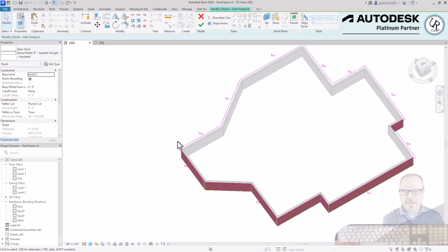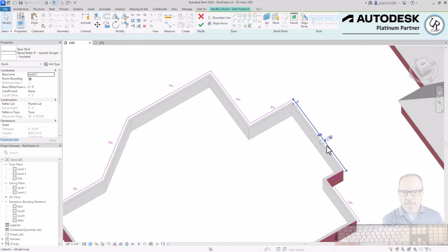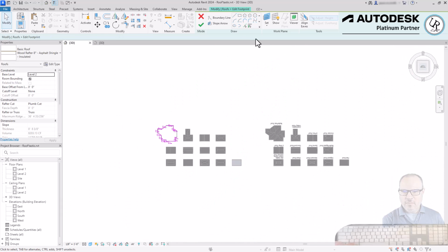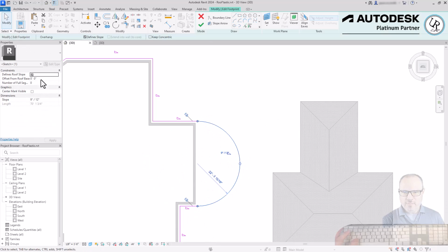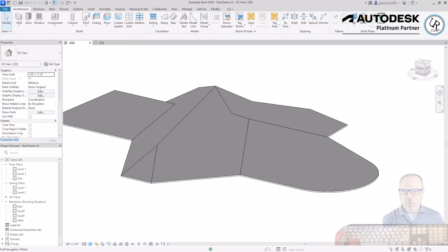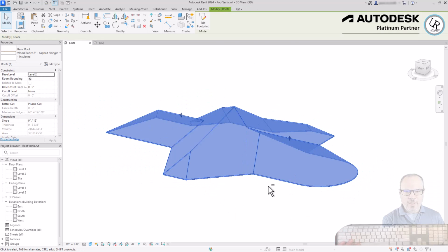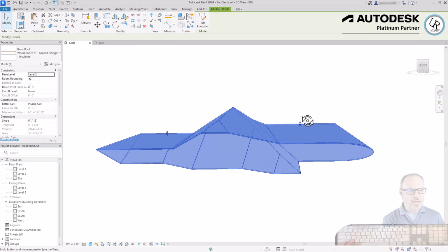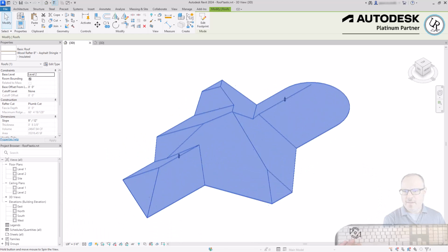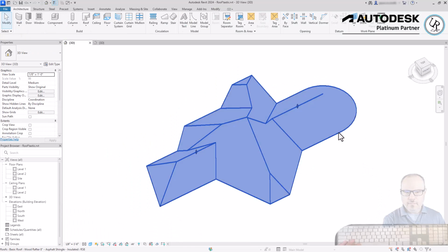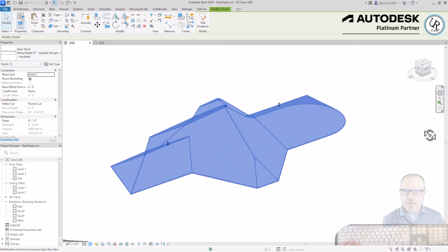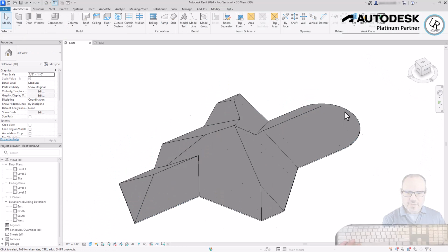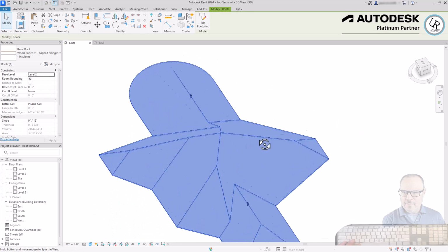Even something more complex, such as creating an arced condition, is capable as well. So if I have an arc here to there, you can actually get curved roof conditions in here, provided all of the adjacent roof slopes are allowing that curve to exist. You cannot exceed the geometry that's available, but Revit will allow you to create complex geometry as long as it can create it.